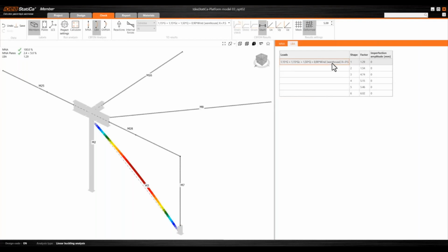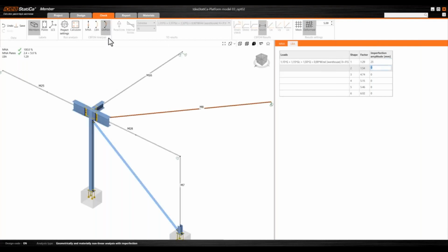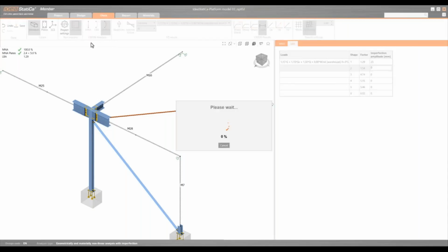And this is something easy. So next to my buckling shape factor, I can add the imperfection amplitude, 24.88. Please note that after pressing enter, the value will be rounded, but only the view of the value is rounded. The software maintains the full definition, and the way we view the values depends on our settings. And of course, I can enter imperfections in any other mode shape.